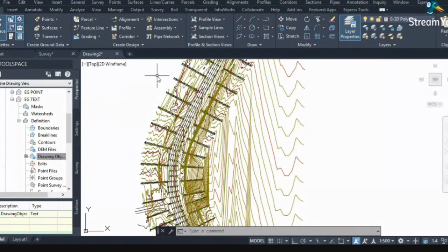I mean, you can look at your contours, you can look at your data, and you can analyze what data you need to create your surface, and you can see what data is useful for you to create the surface. So you can ask your surveyor, okay, give me this in 3D line or give me these things, and you can bring them into C3D and try those elements, and you can see which data gives you a better result.